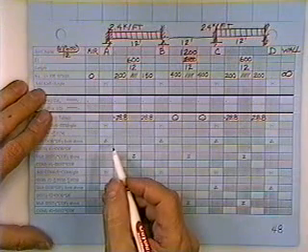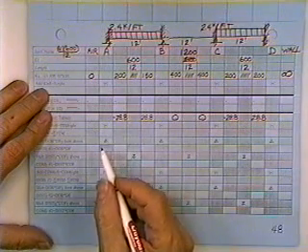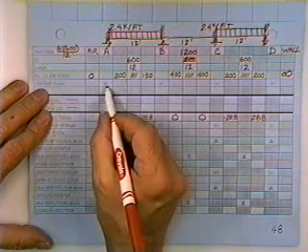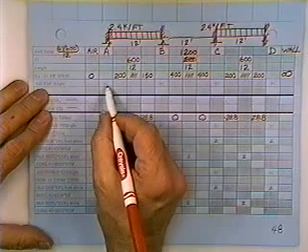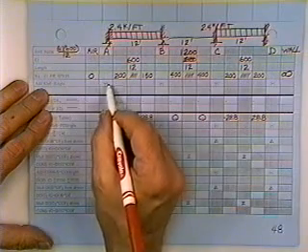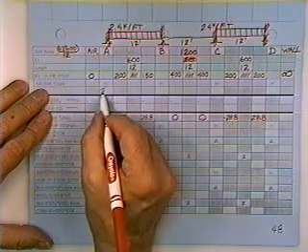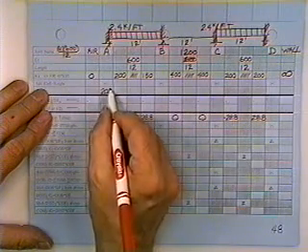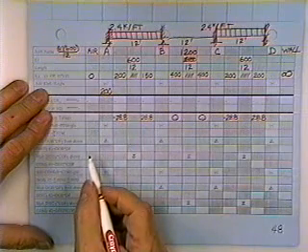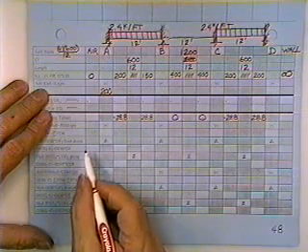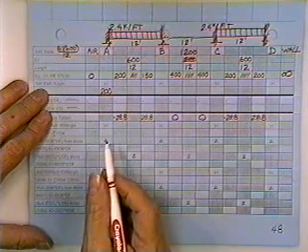Now the next line says, add the stiffnesses to the left and right of the joint, and there's some little arrows there. They're not very big, but they're supposed to show you to go to the left and go to the right and add the two numbers up. And you get a 200 for the total stiffness at that joint. None because of the air, and 200 because of the steel member to its right.